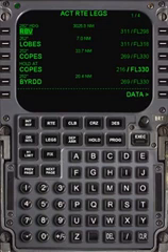Since the throttles are at idle, this will modulate the speed. Normally the FMS allows the speed to vary within a small band. After this, either the throttles advance if the aircraft is below path, or the FMS requests speed brakes with a message such as "add drag" if the aircraft is above path.